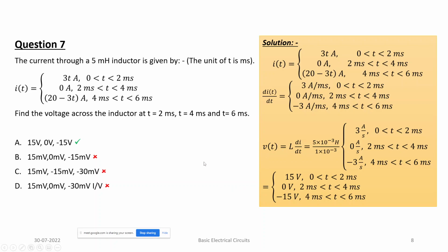Now who can say Faraday's law? Anybody? What is Faraday's law? If any set of conductors is moved in a uniform magnetic field, flux is generated. Because of the flux, EMF is induced. And because of Lenz's law, the EMF opposes it, so E equals minus N d phi by dt. The voltage generated opposes the flux linking that coil, and it is proportional to the rate of change of flux linkage. Yes? Anyone have a doubt?